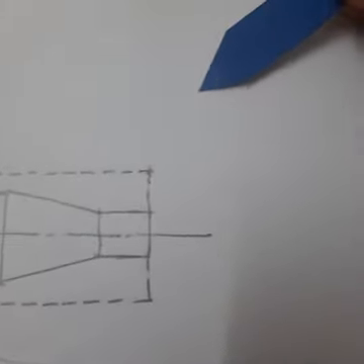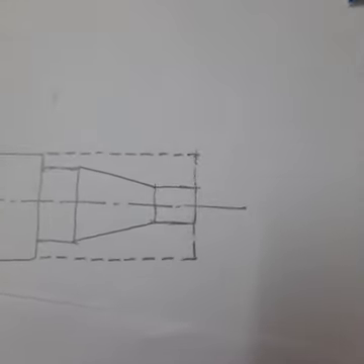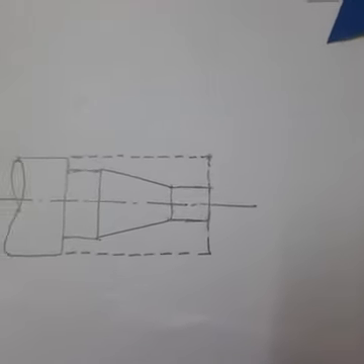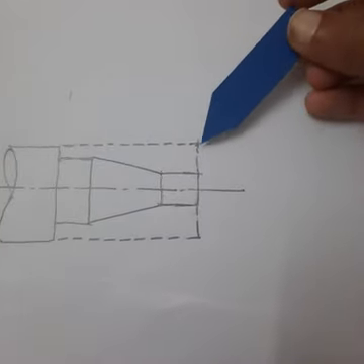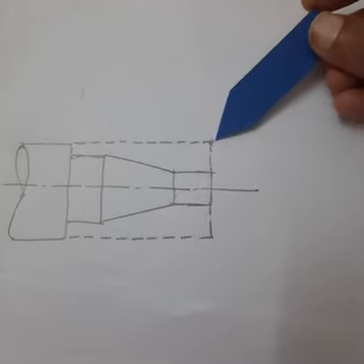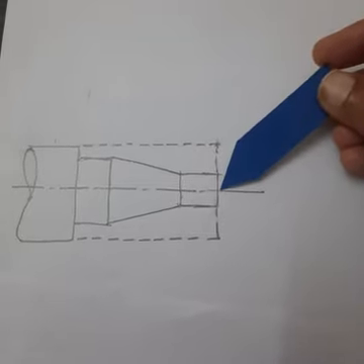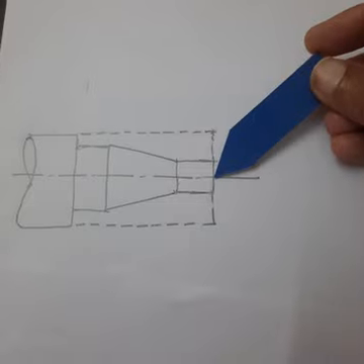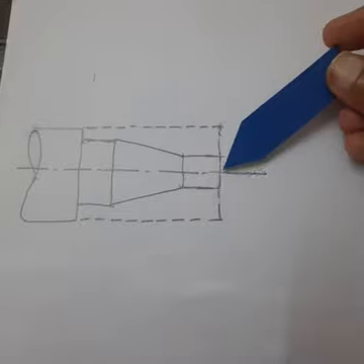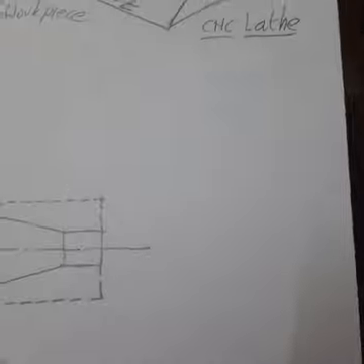So let me show the movement of the tool for the facing operation. Now the tool is at its machine home position. From this point, the tool is taken to this position for doing the facing operation at a rapid traverse. From this point, the tool is moved towards the center at a specific feed rate. Then after that, the tool is made to dwell for a certain period of time. Again, the tool is taken back at a specific feed rate. From this point, it is taken back to the home position.